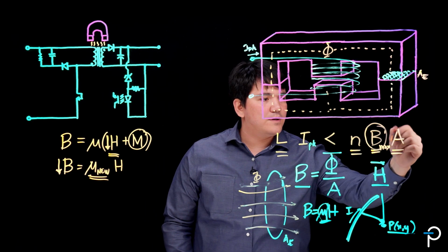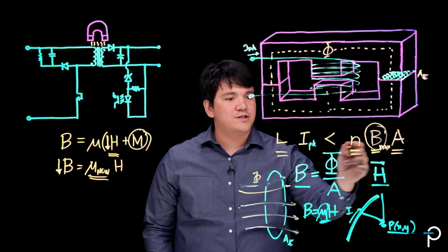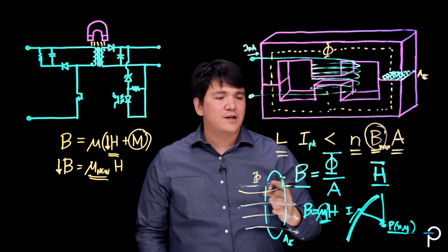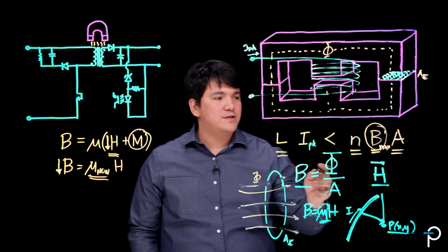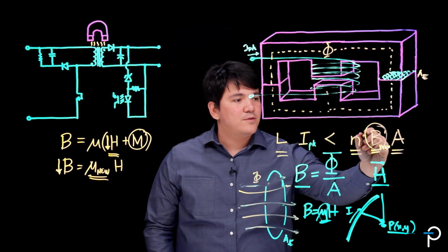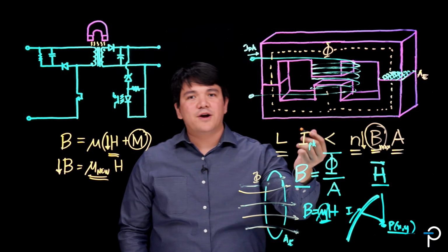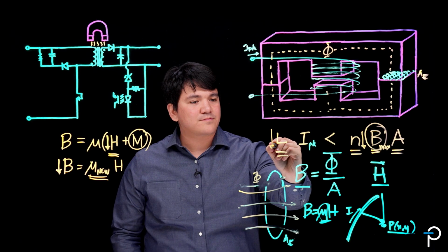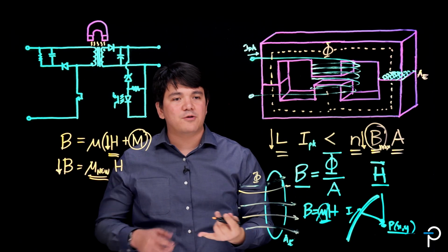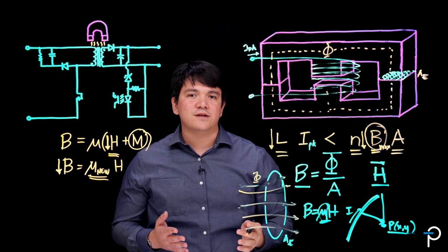Physically, the effective area of the transformer cannot change. Your number of turns cannot change. Your current, depending on your control scheme, could either stay the same or increase, but your magnetic flux density would decrease and your primary inductance would decrease. A decrease in the inductance, again, depending on the power MOSFET, your control design, could compromise your converter's ability to deliver power.